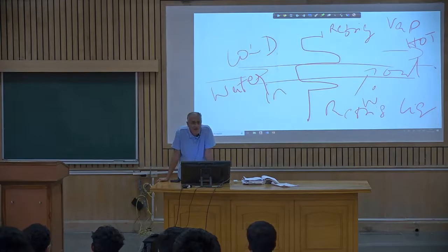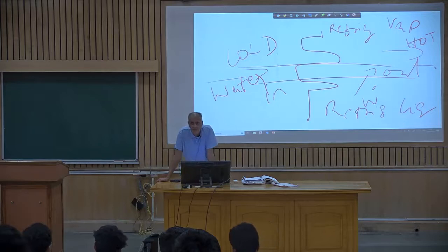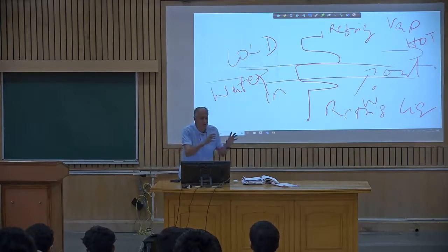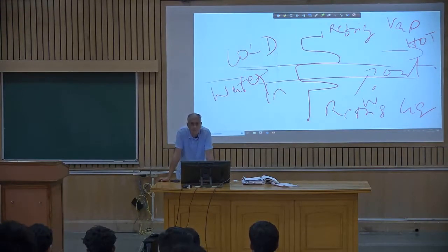So you're riding a bike. What if I give you a sharp left bend? No, you're going to go hit the wall. Obviously, yes. Get it? You have to have a gradual change. It's the same thing. You're moving like a fluid. You need to give gradual changes in area as well as directions. Otherwise, it will hit the wall and it will get accumulated there. So, inlet to outlet, you will have area changes.